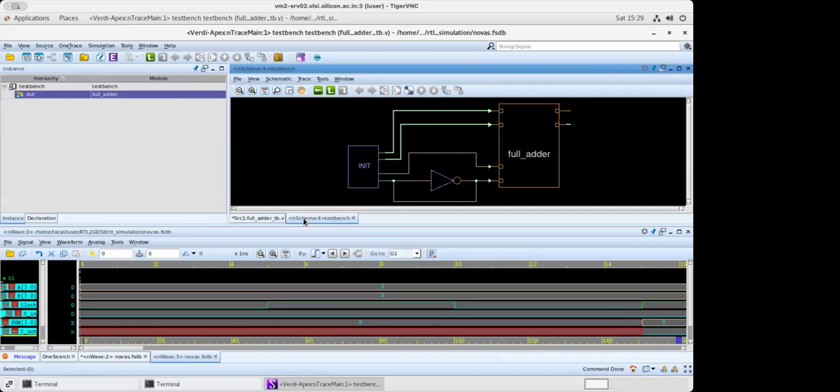So in the left corner, there is a small window. It's written test bench, and under that test bench there is something written as DUT, design under test. Now just click here, select this. Then in the above, there are certain icons. One is a waveform icon, another is an AND gate. If you hover your mouse, it will tell you it's a schematic. Just click that particular symbol. It will open a new window. It is a kind of schematic, the top level RTL you have designed.